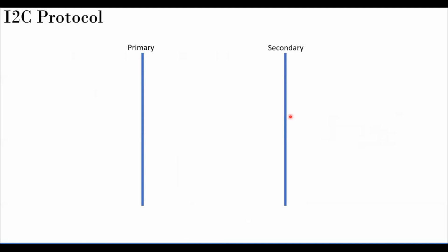Okay, so coming back, how does it work? I said I can connect 2 raised to 7 devices, right? But how is it possible? Let's say this is the master here. I would like to call it primary and secondary rather than master and slave, but if somebody is keen, this is the master, this is a slave. So how does the I2C protocol typically work? The foremost step is to issue a start, basically I2C start, plus the 7-bit address that I'm interested in. Let's say I have 128 devices. The first device obviously will have the address 0x0, I mean 00, whatever.